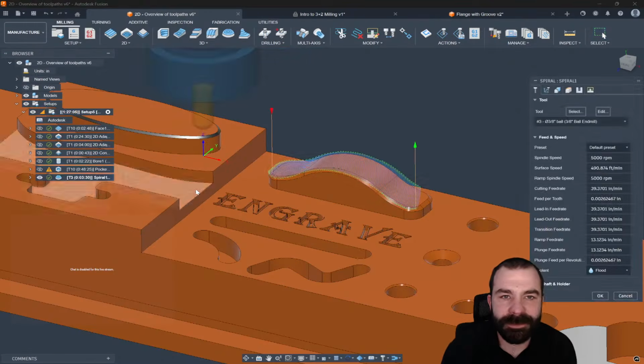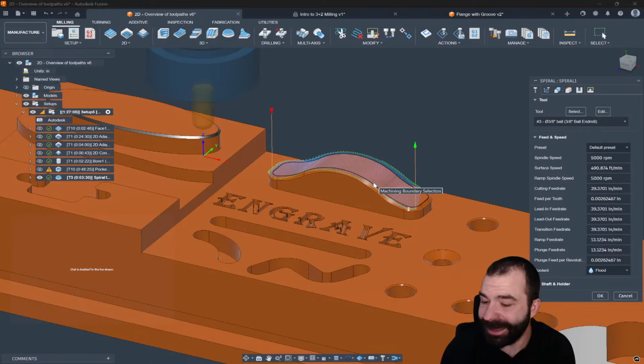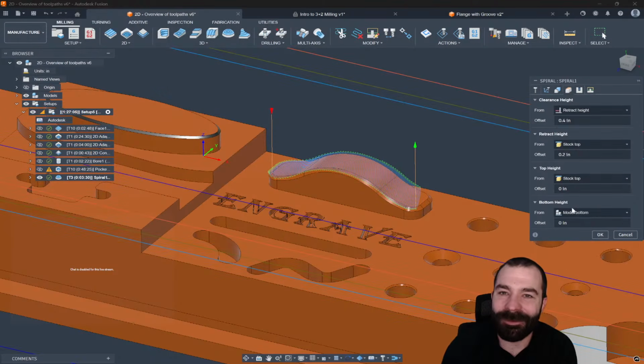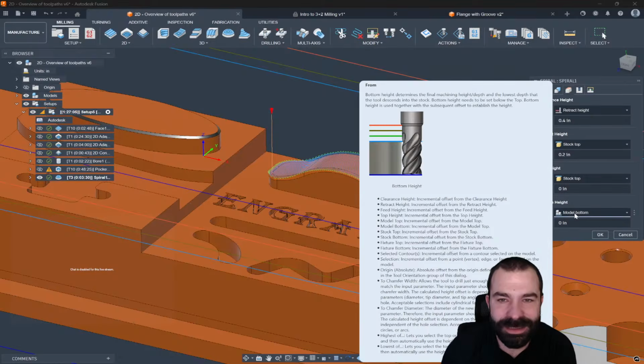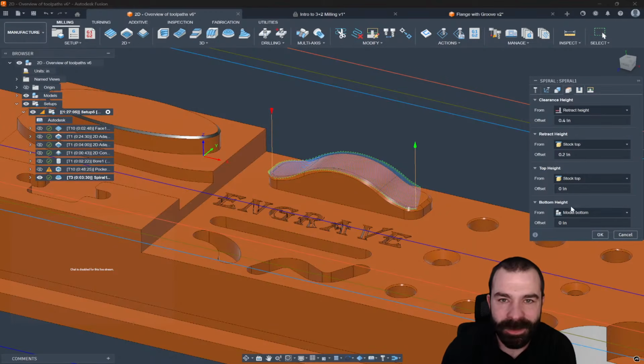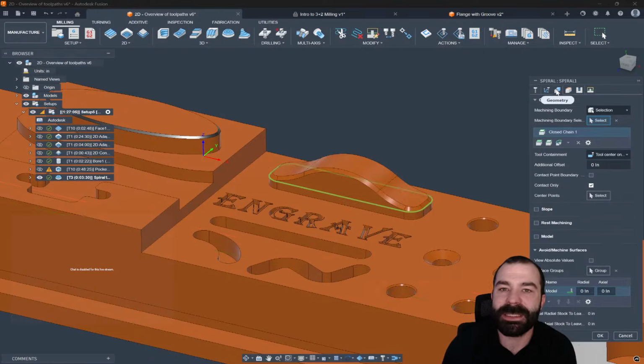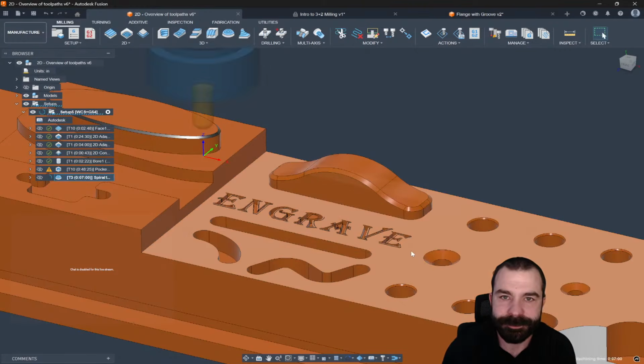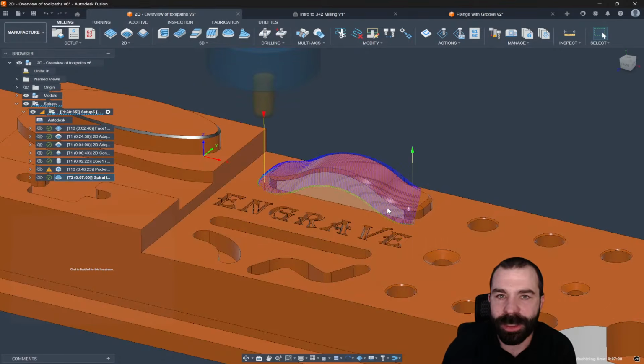From here, I did a spiral toolpath for some reason. But notice right now, my heights tab is currently set to model bottom. So changing anything I can here is never going to actually get that toolpath to go further out and around my part. So this is why it's so important to move left to right, top to bottom, because something as simple as, well, what if the tool was outside of that boundary? And now you'll notice we're going all over the place here.